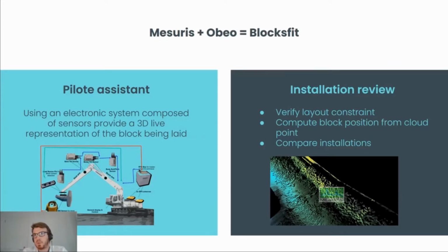The other part of the project was about providing some analyzing tools on the construction site that could verify some constraints, density, orientation, and stuff like this that are required to verify the quality of the construction. And also provide a way to compute the exact position of blocks from a point cloud. This could be really useful if you want to verify the stability of your dike after, let's say, a storm. After a storm, the blocks could have moved and you want to verify there is no breach in your dike. So you use this kind of software to do that.